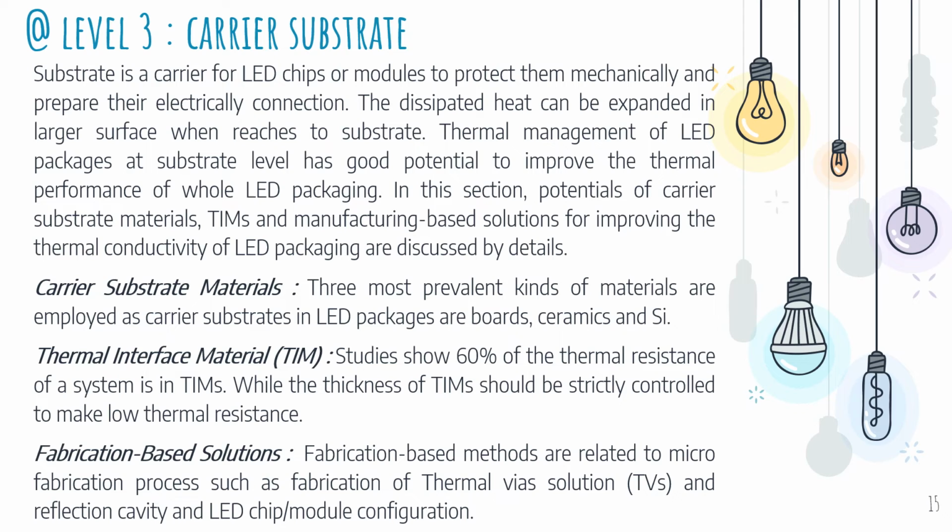In level 3, the substrate is a carrier for the LED chip or module to protect them mechanically and prepare their electrical connections. The dissipated heat can be spread over a larger surface when it reaches the substrate. Thermal management of the LED package at the substrate level has good potential to improve the thermal performance of the whole LED packaging. In this section, the potential of carrier substrate material, TIM, and manufacturing-based solutions for improving the thermal conductivity of LED packaging are discussed in detail. The 3 most prevalent kinds of material used in carrier substrates are board, ceramic,